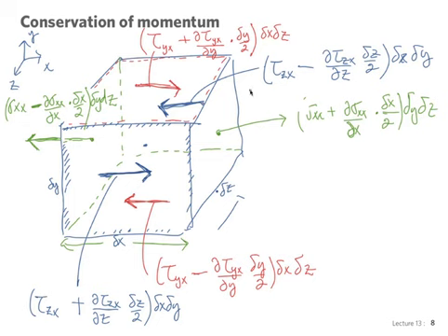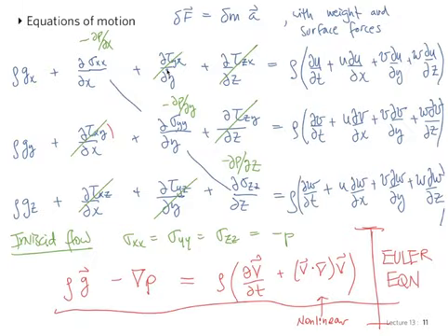And by looking at all the components of stresses in that direction and just doing Newton's law, force equals mass times acceleration, we were able to derive the equations of motion. We got up to that point. The full equations of motion are shown in blue, just by doing force equals mass times acceleration for a very small element of fluid.